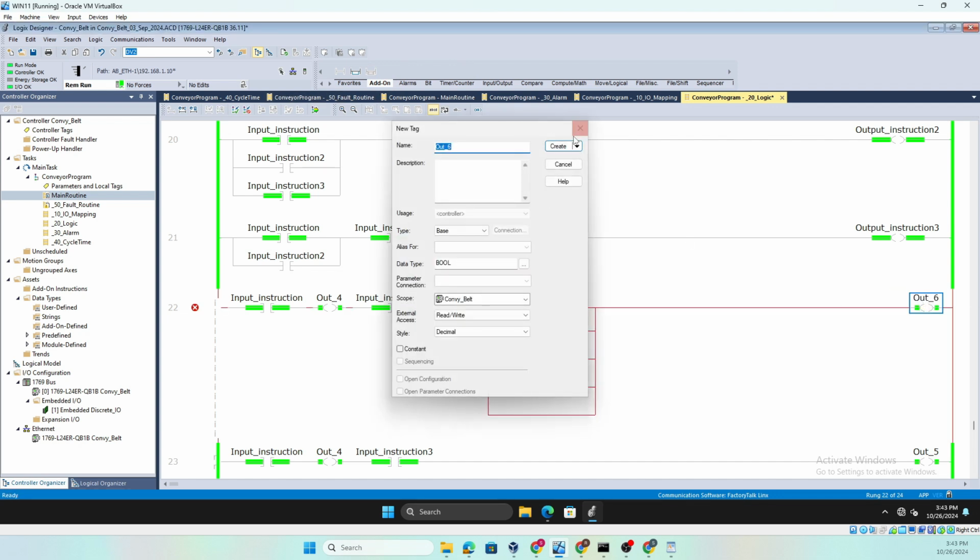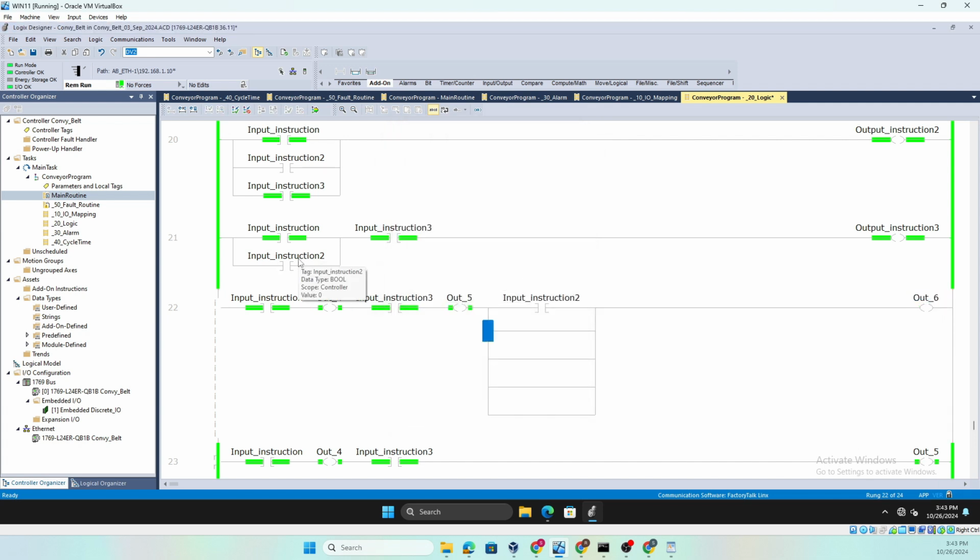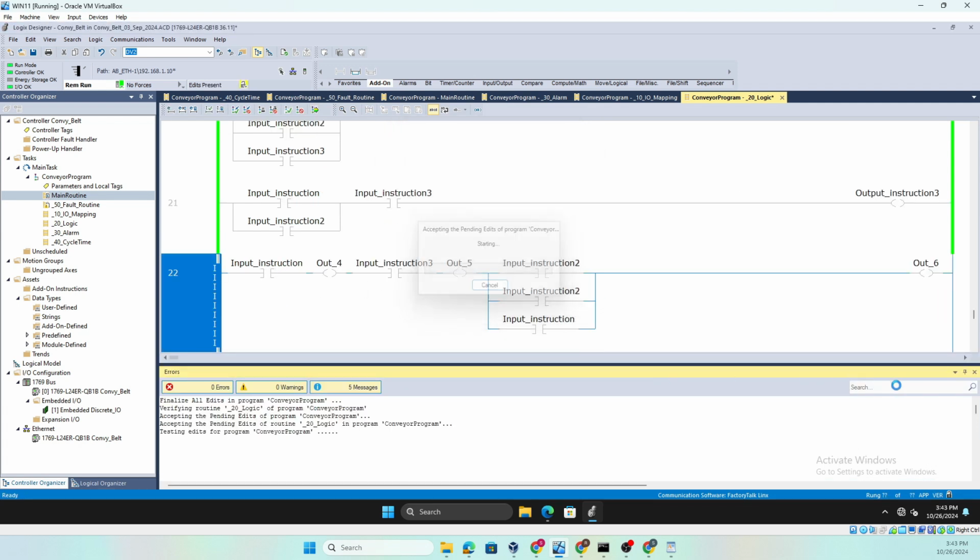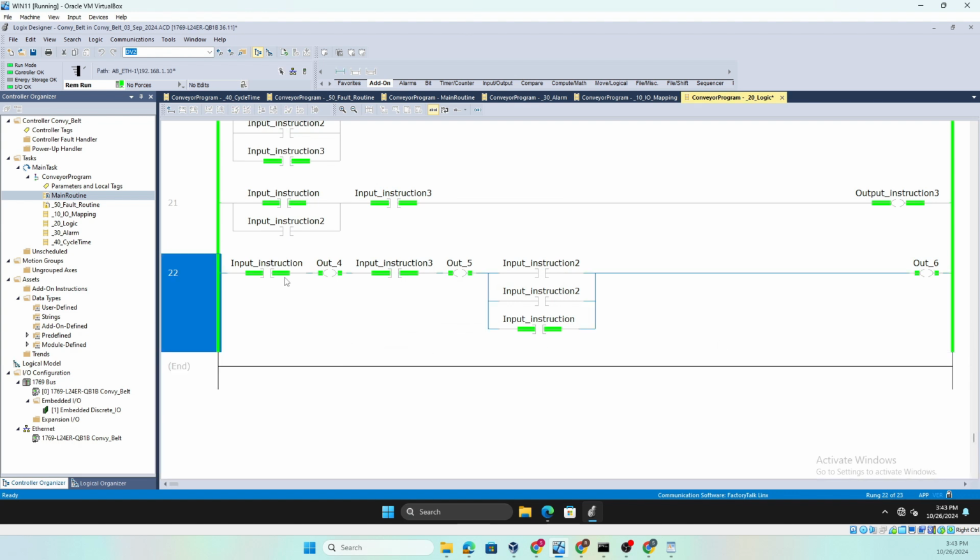We call it a new output 6 here, and some people do this. So on this one, very interesting, right? So I have my rung in condition true, rung out condition true, and this condition is true. Since this rung out condition is true, it will execute this instruction. What if I toggle that low?